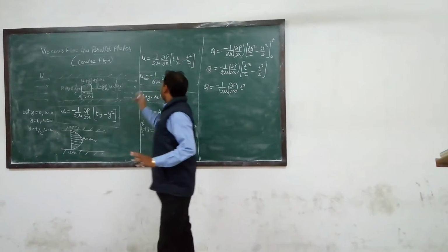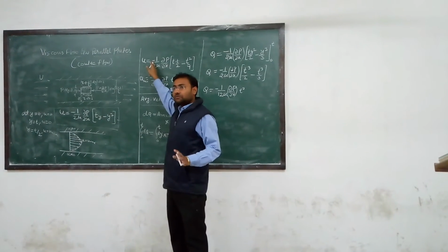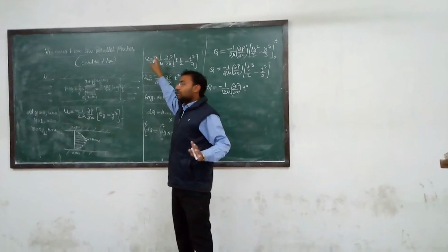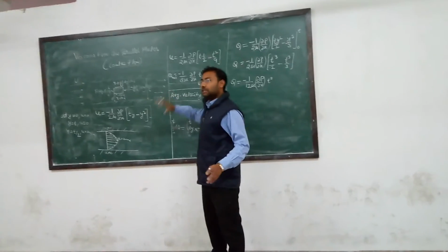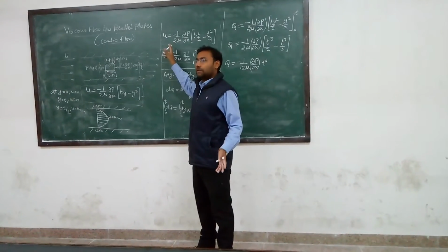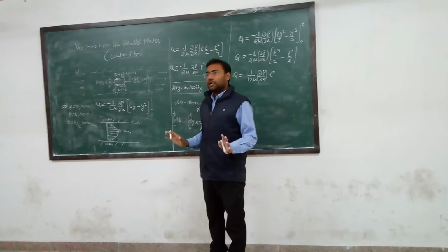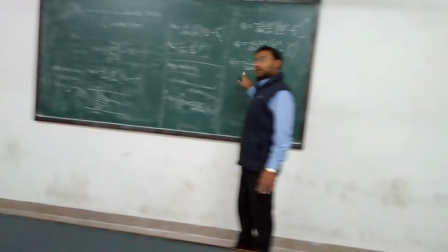Okay? And the velocity has a minus sign in this. So from previous, you know, the minus sign indicates that ∂p/∂x must be negative. Pressure must decrease in the direction of flow, because velocity is positive. For positive velocity, the sign of ∂p/∂x must be negative. Similarly, okay? So we have calculated the discharge here.